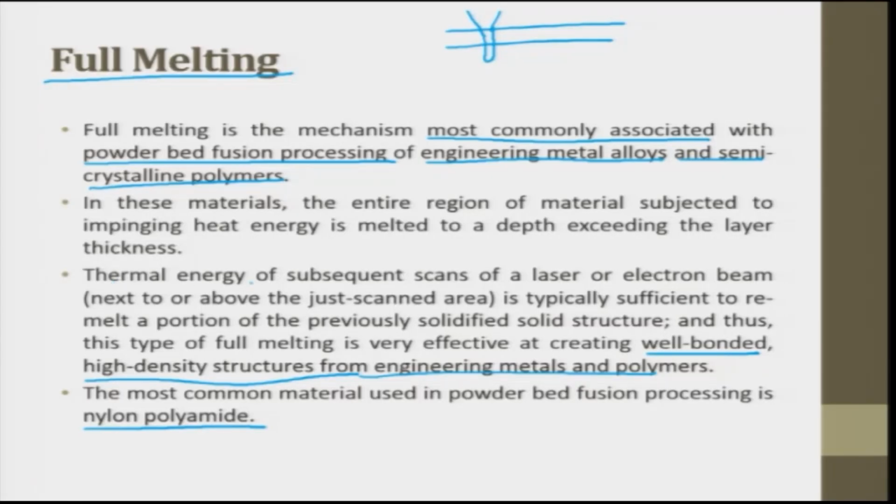So, the thermal energy of the subsequent scan of a laser or an electron beam. So, you can use electron beam, but the only advantage of laser is it can be used even in vacuum or non-vacuum system, but electron beam pushes you to use a vacuum system. It is typically sufficient to remelt a portion of a previously solidified solid structure, and thus this type of full melting is very efficient at creating well bonded high density structures for engineering metals and polymers.